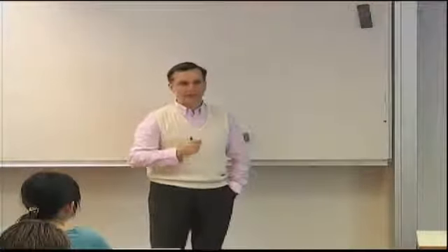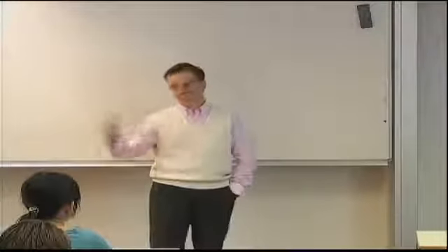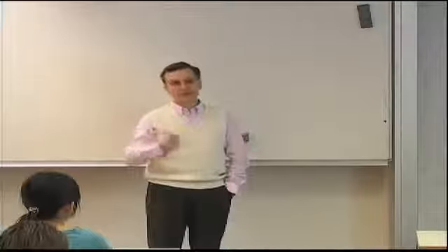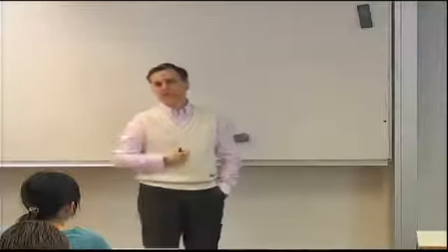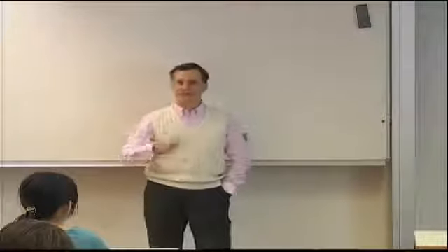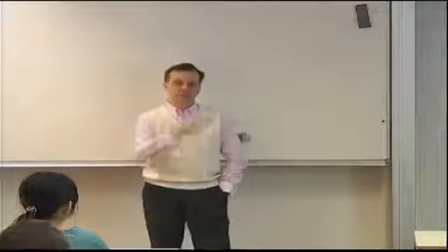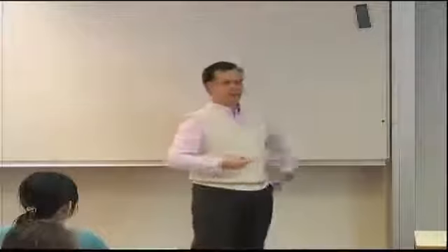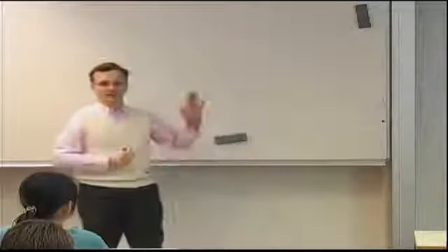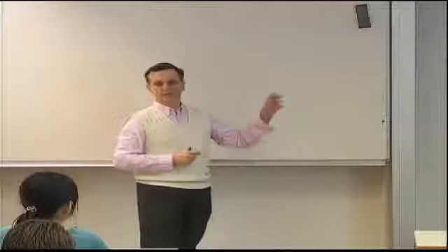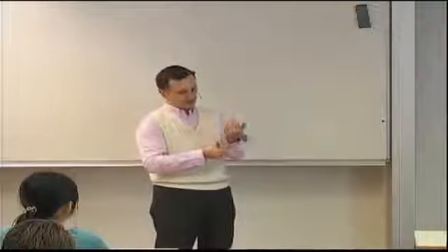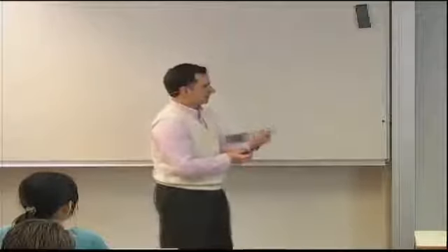That does not mean that you shouldn't check all the other Mx, My, Mxy and see if indeed one of the two laminates is significantly worse because one of those quantities is much higher, and therefore you would have a failure in a different mode than the one we're considering here, which is under pure compression. In general, as a very good start in these problems, Nx is sufficient, but then once you start finalizing your design, you should look into the other quantities also.